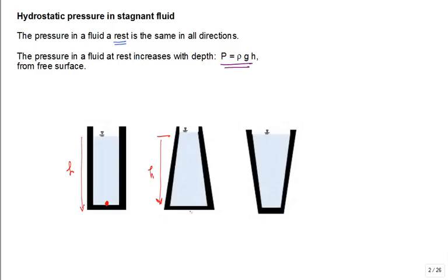We just said that the pressure, rho g H, is due to the weight of the fluid above it. Let's call this case A, this case B, and this case C. In fluid statics, the pressure is due to the weight of the fluid above it. This one has an increasing area, so I've got more fluid above me. It must have a greater weight or a lesser weight.